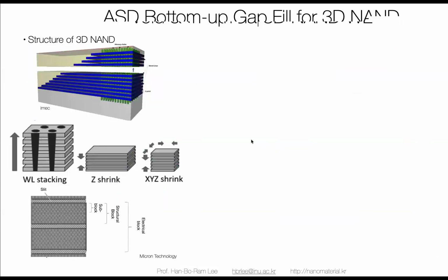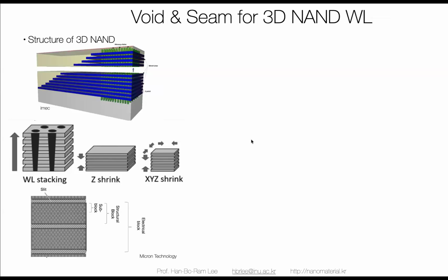And this is the last part of the NAND flash memory. Oh, not the last part. Okay. And this is the very well-known three-dimensional NAND flash memory structure. All of the narrow lateral lines are word lines, so they should be deposited by tungsten ALD. But the problem is we have to increase the number of these steps a lot. This is the high step approach.